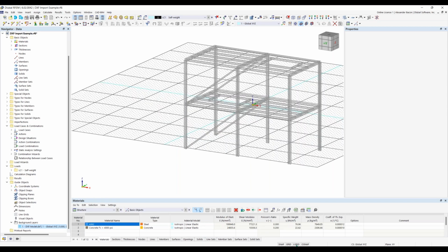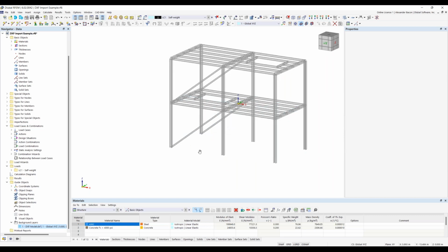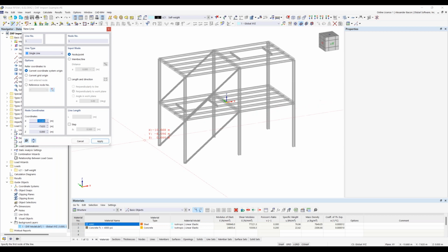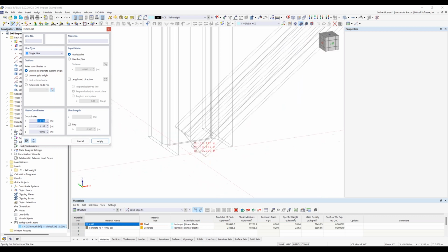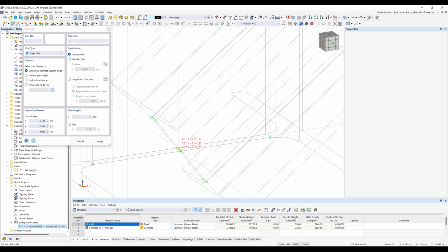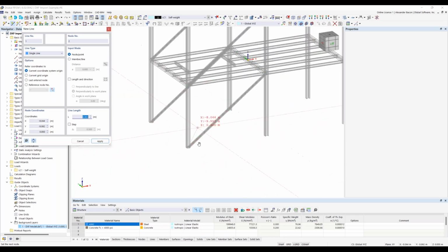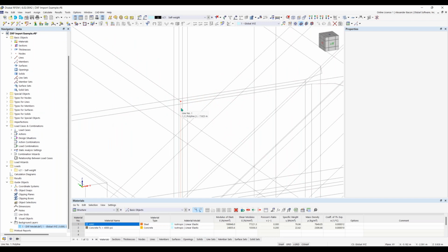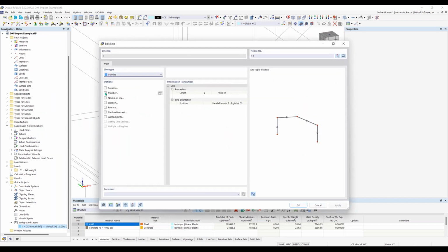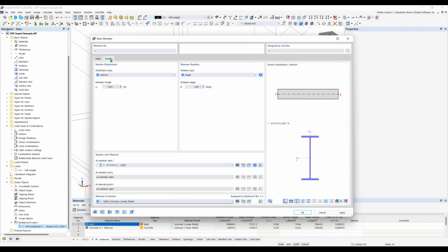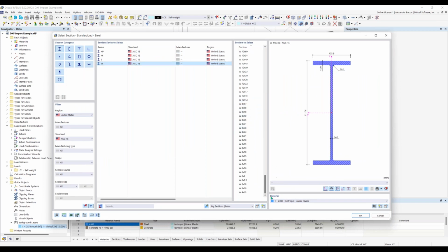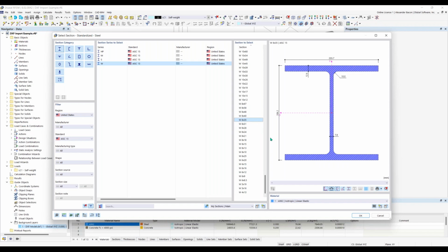So now we can use these background layers to model this. This is similar logic to the IFC file that I showed. And I'll just do an example real quick. So we can draw a line, a center line again. I'm going to use this column again as an example, so I can zoom in here and snap to this point if you have your object snap settings turned on. And then I'm going to go to the top here, and I can snap to this point, right click, and then I can double click on the center line, check on the member option to turn this line into a member, go to section, and then I can quickly go to W shapes, and I can scroll down, and this will be in 8 by 35.